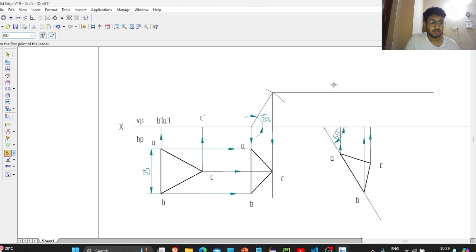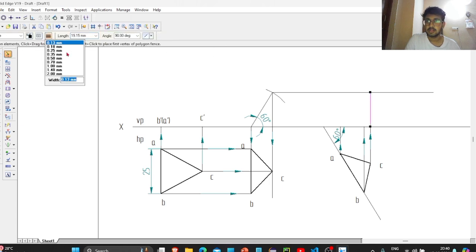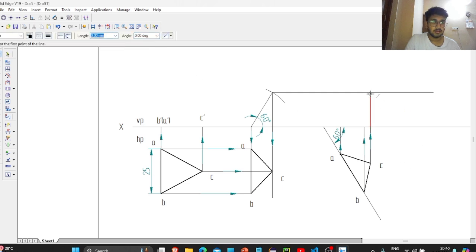Like that. Now one of the lines should extend all the way to the top. Is this line over here? Sorry, a line has been a mistake. We'll take this, leave it till there, and see, this line should be at 0.5 mm thickness, thick line. Next, we'll just try to join the line like this.